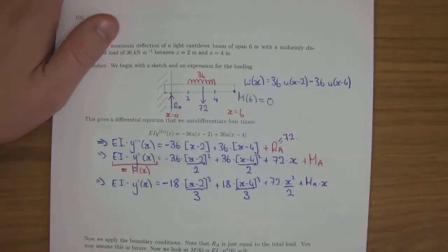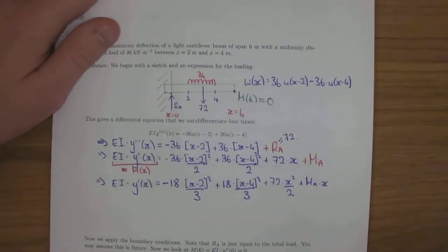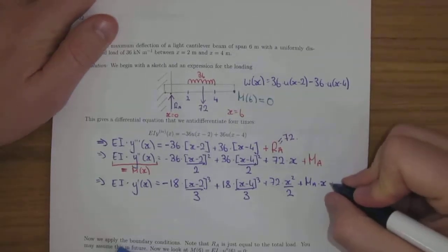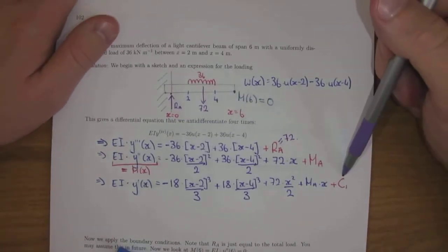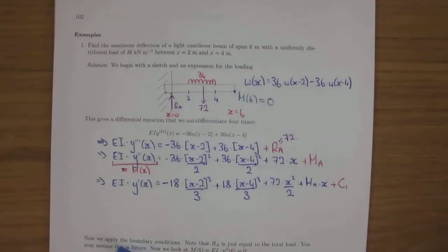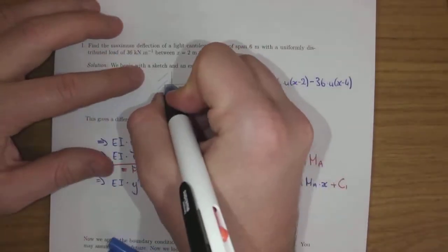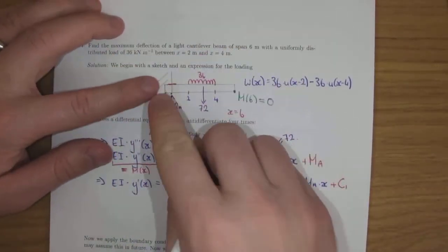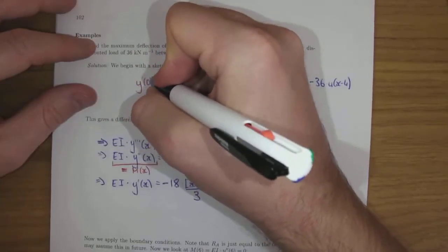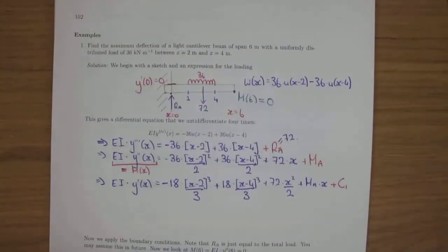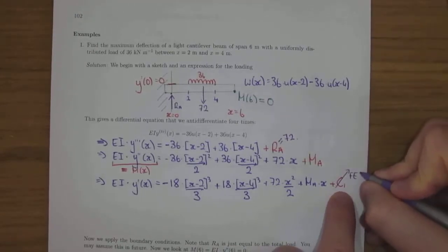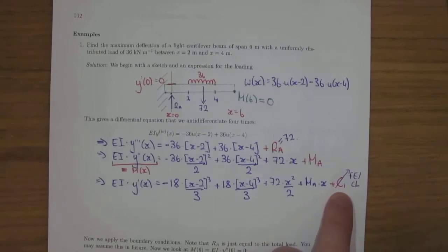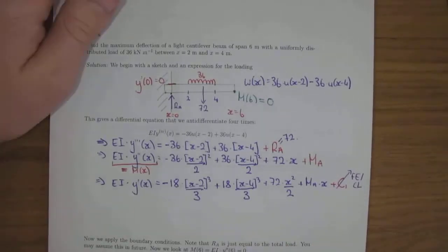And even though I'm going to say that C1 is 0 in just a moment, I still think you should write it in. Because if you get into the habit of leaving it out, and you do a simply supported question, you're in a world of pain. C1 is proportional to the slope at 0, and because it's fixed, it comes out straight. Look, that's flat. Slope at 0 is 0. And so C1 is proportional to that, so C1 is 0. And that's also the case for fixed ends and cantilevers, but not simply supported, which I've said enough times now.